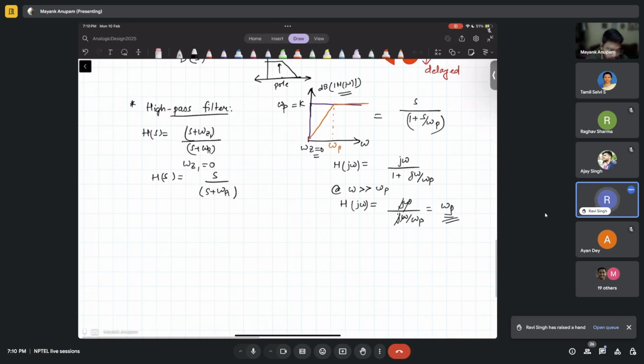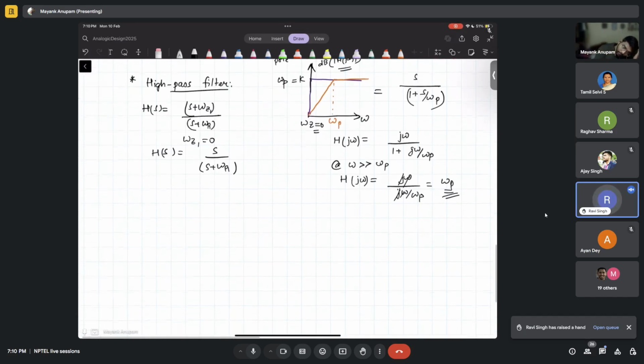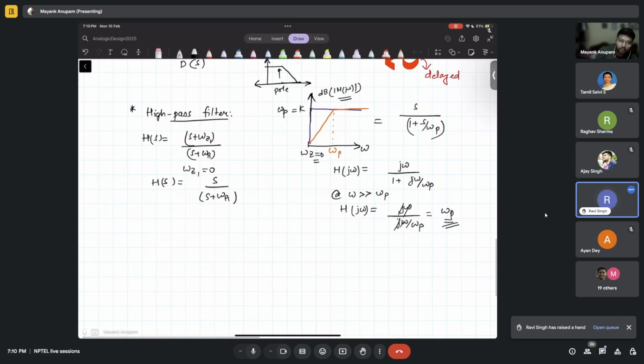Yes. So for the standard analog electronics form, which is 1 plus s by something, if they are non-zero, we can look at that. For zero at the origin, we always have to refer back to this form. So if you take omega z1 out and omega p1 out, how will this look? 1 plus s by omega z1 divided by 1 plus s by omega p1, right?